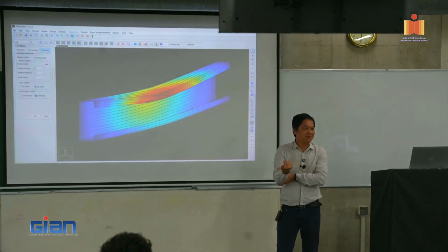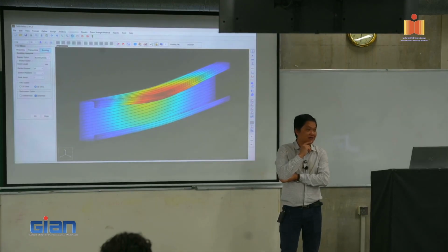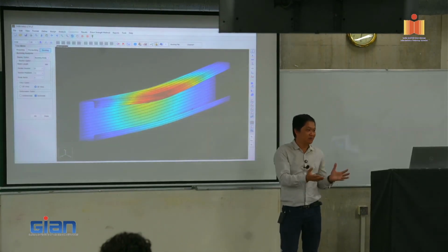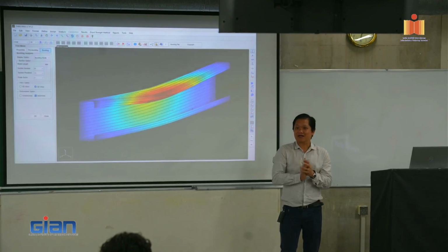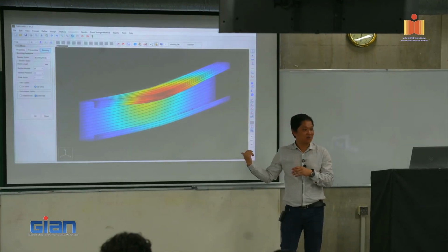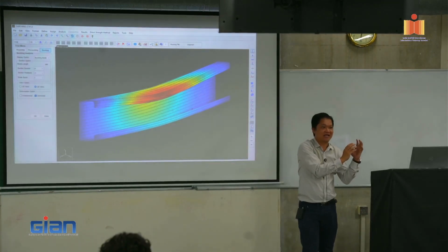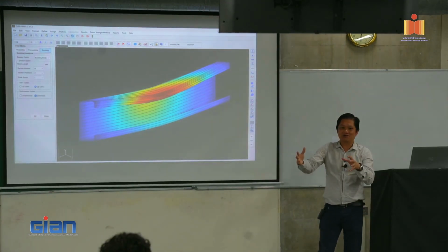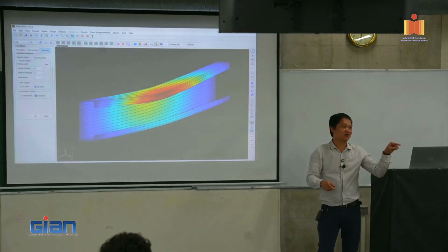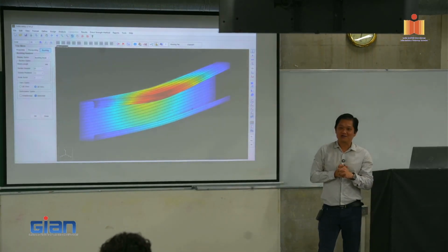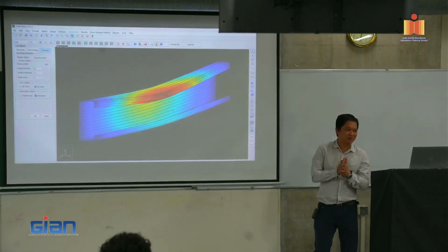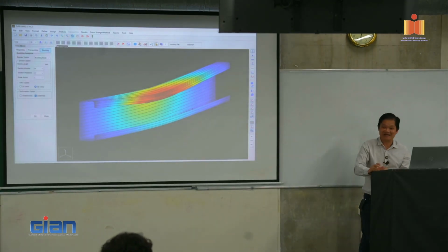And the other very important job that we need to do is Py, how to work it out, the U moment, U model, plastic mechanism model for localized loading. And once we finish that one, you're going to have a beautiful, nice direct strength equation for web crippling or for those types. So you got THIN-WALL, you run that, and then you got a model that we're developing now for Py, put all together in one equation for DSM, and then you got the load that you want. So it's in future. We're developing now. I promise you, once we have that, we will share with you, okay?